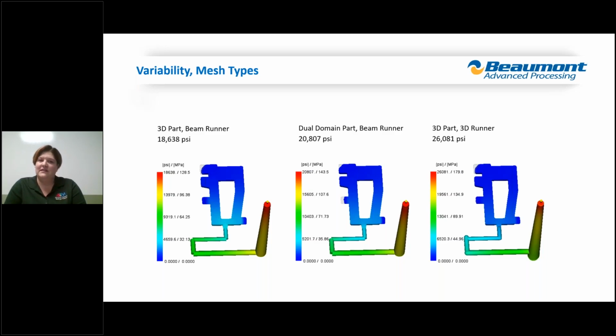Even within this same material card, I'm getting roughly 7,500 PSI difference. And really that's just showing you the solver differences, right? Now this is polycarbonate, so it might be exaggerating it a bit more than if we looked at polypropylene, but there is variation just in the characterization.